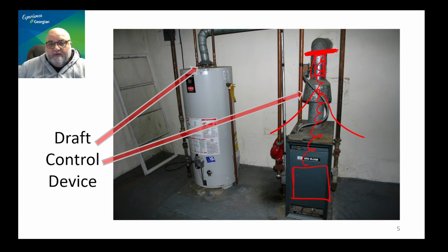It is important that we don't spill combustion products into the building. We have talked about that. However, in this case, we're choosing the least of two evils. One is to spill those combustion products. The other option is to have nowhere for the combustion products to go at all, and they just accumulate here, in this pipe. Which one do you think is worse? Worse is not having a place for the combustion products to go. It is, as much as unpredictable, it will end badly.